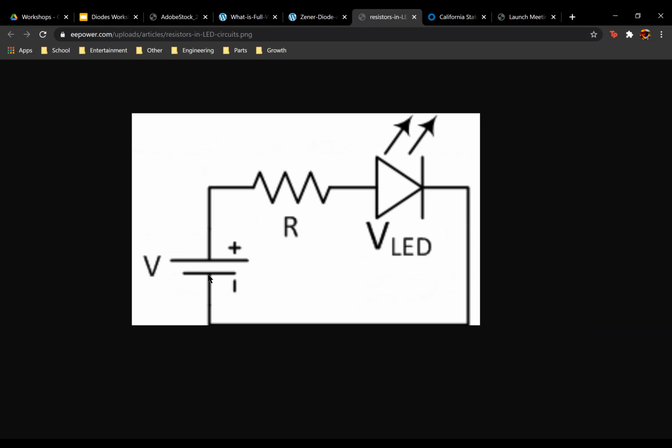So what we would like to have you do is solve for this circuit. We're going to say that our battery is rated at 10 volts. Our resistor value is unknown, and our LED has a 2-volt voltage drop when 1 milliamp flows into our circuit. You can solve this using Ohm's law, and I'll give you guys like 2 minutes to solve this. It shouldn't be that hard. And then we'll go over how you would solve it if you weren't able to grab it.